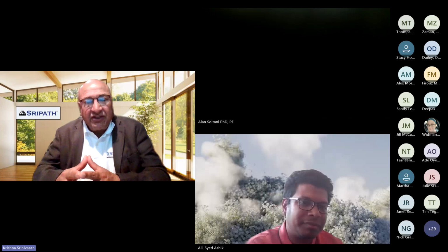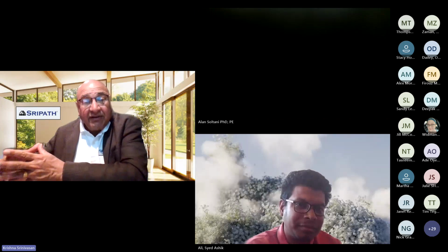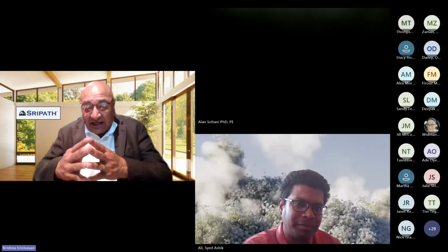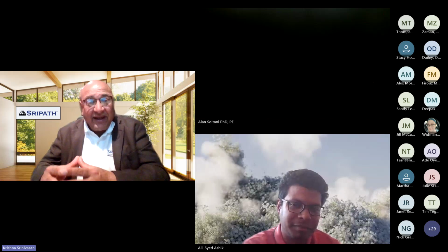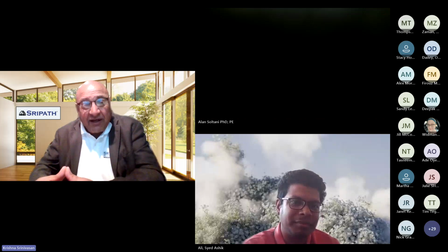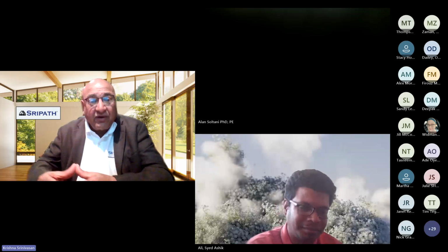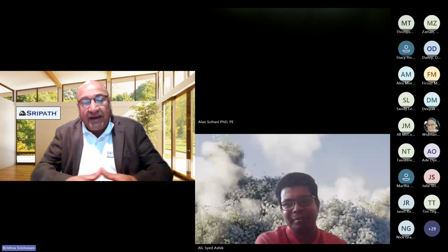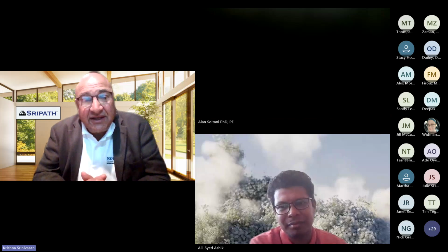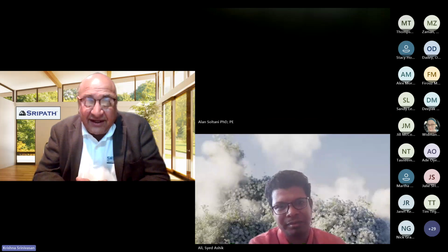You don't work with, geez, has this material been recycled 4 times over? You don't do that. What you do is, I got this mix from the side of the roadway. I need to put it back into the roadway. How much of this can I put in? And what levels of rejuvenator? What is the impact on rutting? What's the impact on fatigue? What's the impact on cracking? Those are the kinds of questions that folks are answering.